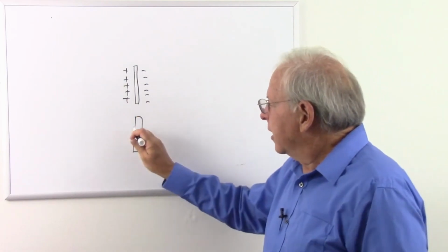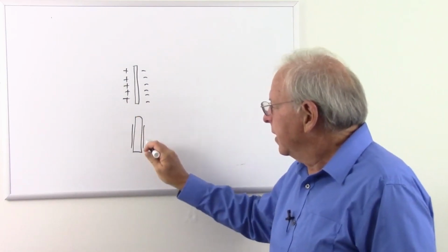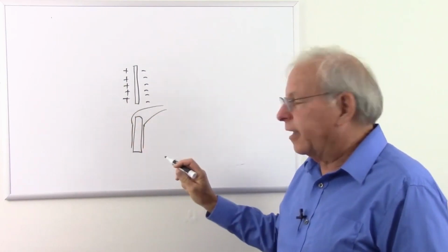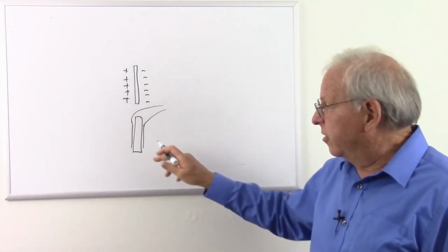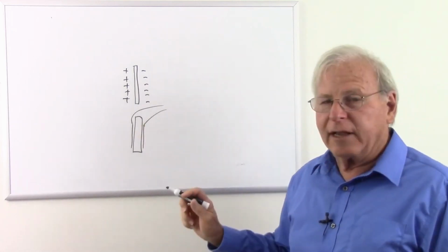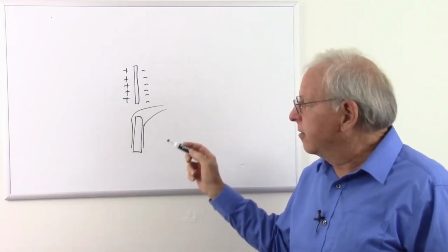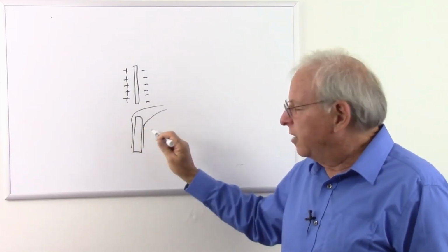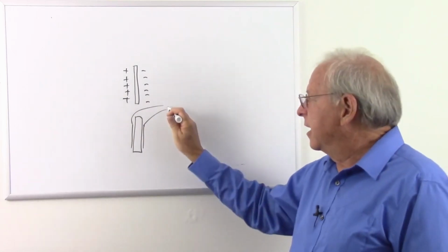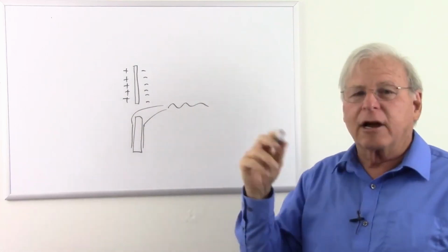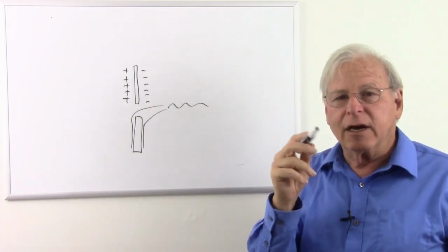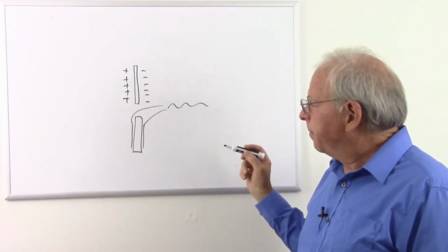So there would be a couple of plates on there, and with wires on them, looks sort of like a capacitor. In fact, it does have capacitance because we have two conductors separated by an insulator. But in the case of a crystal, the piezoelectric effect causes it to produce alternating current as it vibrates, and we can take that alternating current and amplify it. We'll talk about that kind of thing in the analog circuits at another time.